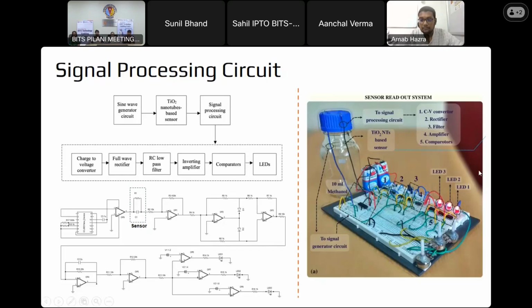On the right side, you can see the circuit we developed in the breadboard structure, and the sensing chamber. We can place the sensor inside this chamber, as I have mentioned in our schematic. And of course, the contaminated solvent or contaminated beverages can be placed inside the bottle. A small quantity will be fine for testing. We have used 3 simple LEDs, which will glow at different contamination conditions of the target solvent. Other than these LEDs, it can be represented with a display screen for more accurate representation of the methanol contamination.